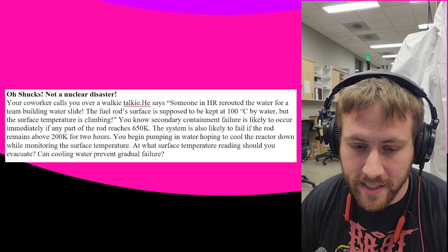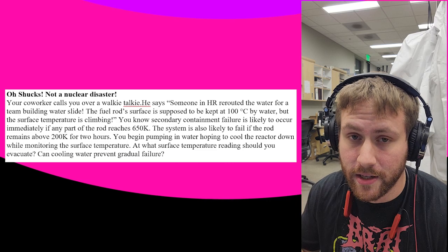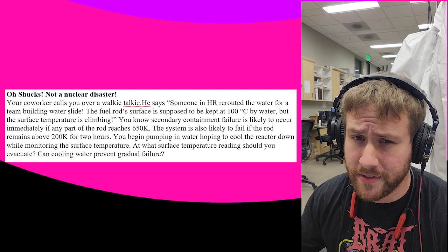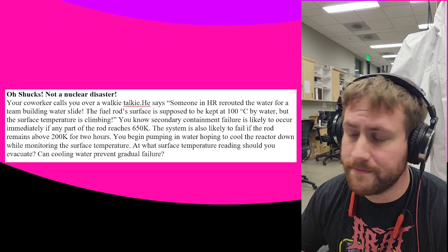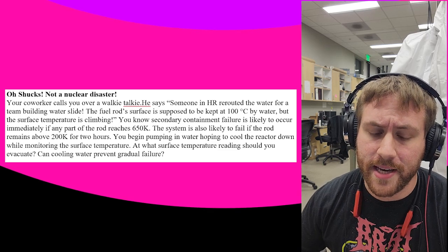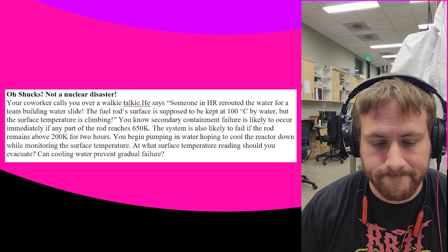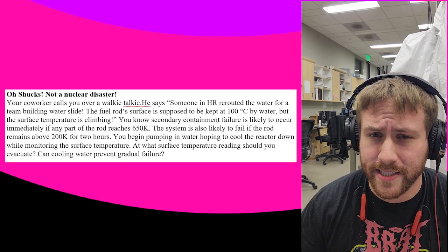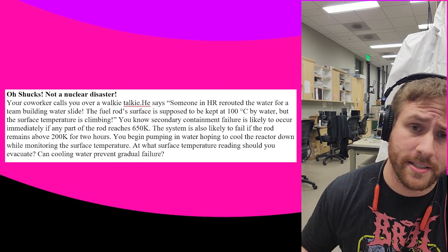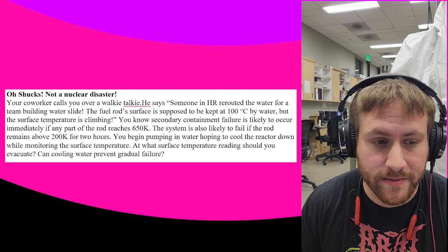So today we're just going to look at the first case of the failure at 650 degrees Kelvin, and we're going to make a pseudo steady state model relating the surface temperature, which you're able to measure through some sort of thermocouple on site, and using a pseudo steady state model to see if the center of the rod will reach 650 degrees Kelvin. And then during recitation, we'll address the second case, the transient case, regarding the 200 degrees Kelvin.